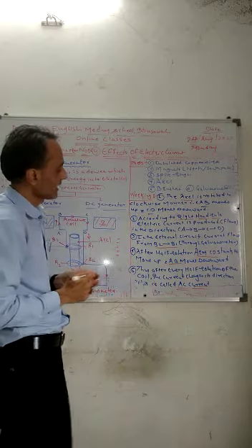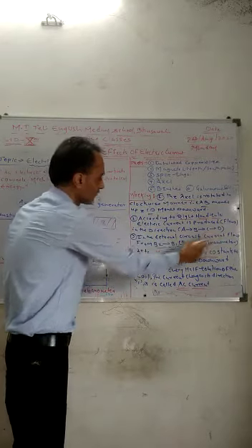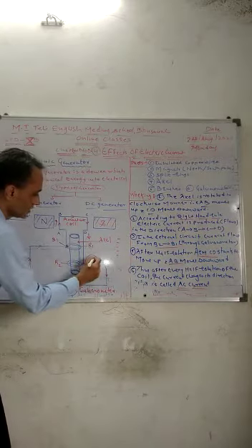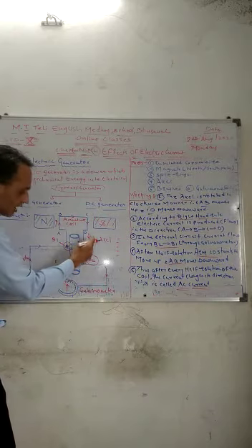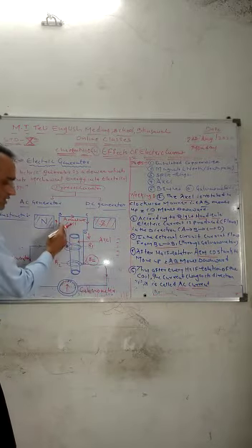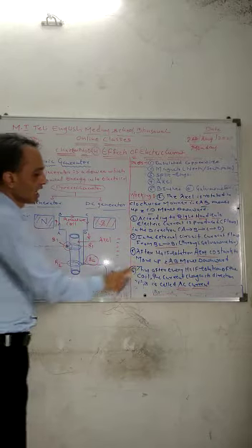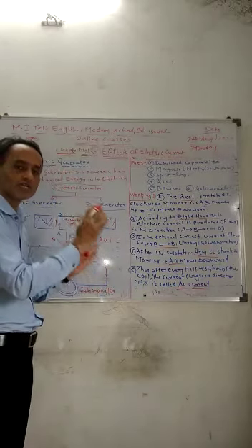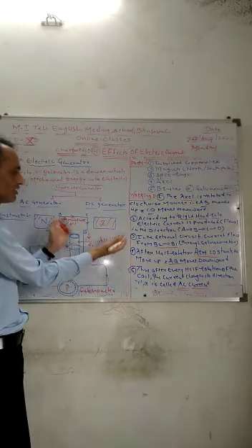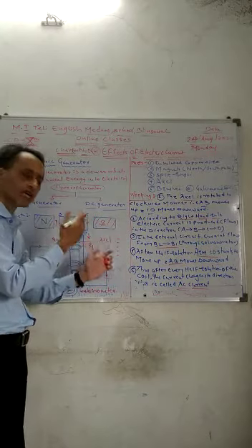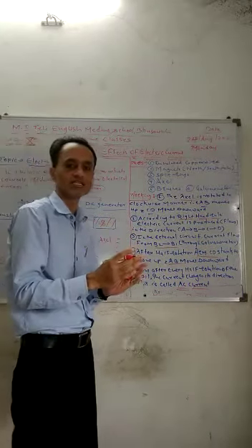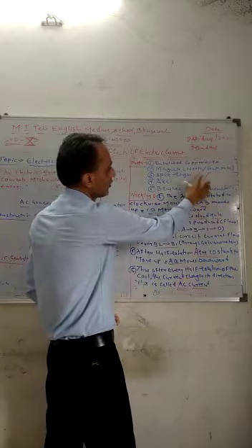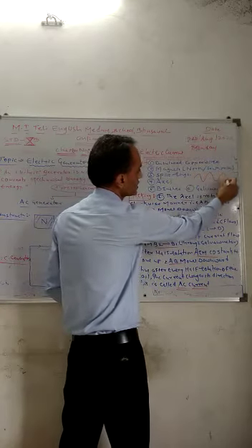Next, in the external circuit, current flows from B2 to B1 through the galvanometer. You can see the carbon brushes B2 and B1 over here. So the outer circuit, the current flows in this direction, from B2 to B1. After half rotation, arm CD starts to move upward. As the half rotation is completed, now the CD arm is going to move up and the AB arm is going to move down. So what happens? The direction of the current changes. So basically AC current is like this. This is the alternating, means upward downward type of current. This is called the AC current.